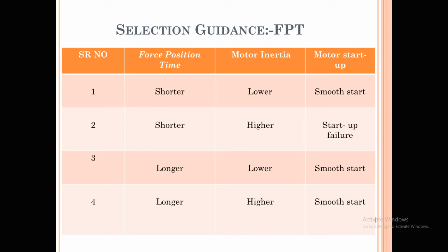In another condition, if your motor inertia is higher and you are selecting the higher value, in that case also the motor will start smoothly. So these are the observations that I have experienced when I am doing these activities. These are not actually a guideline, just a thumb rule. Whatever observations I have gone through, if you are going for tuning, you can consider it as a reference.